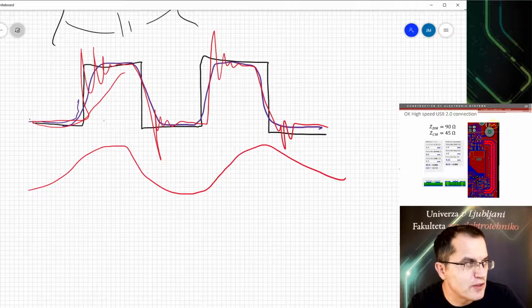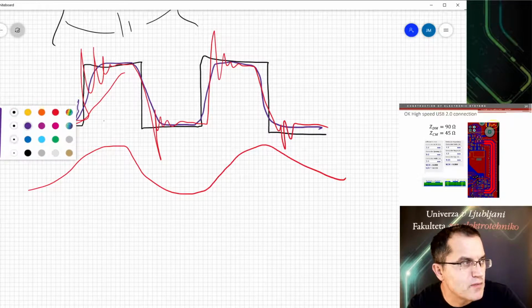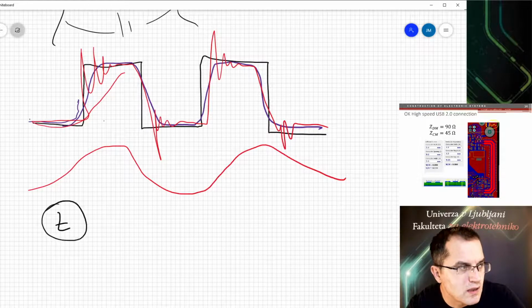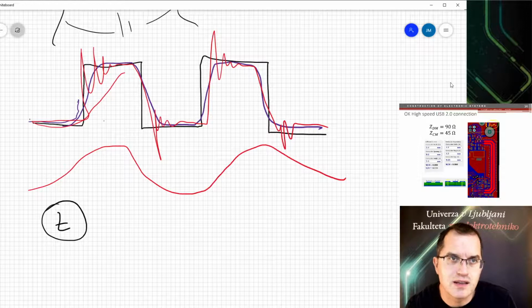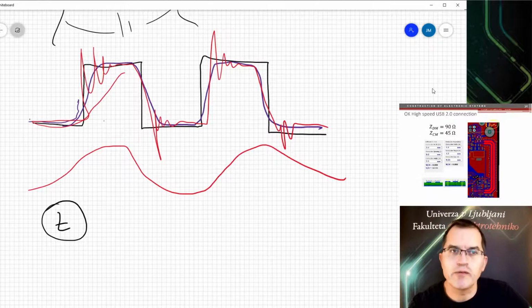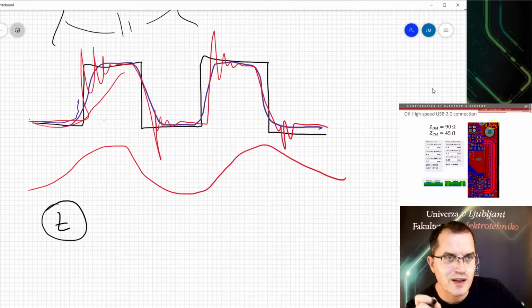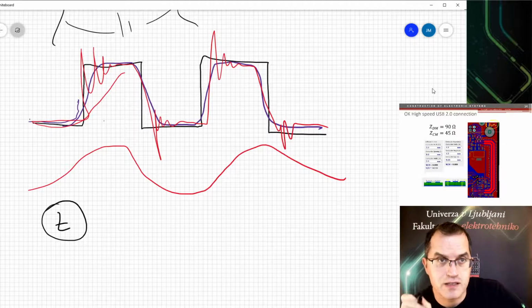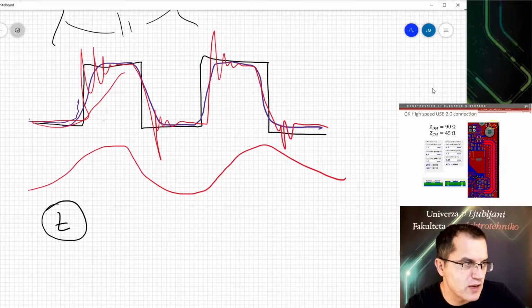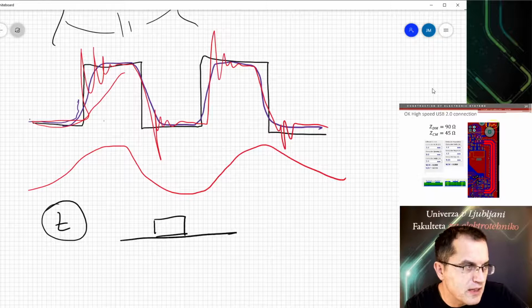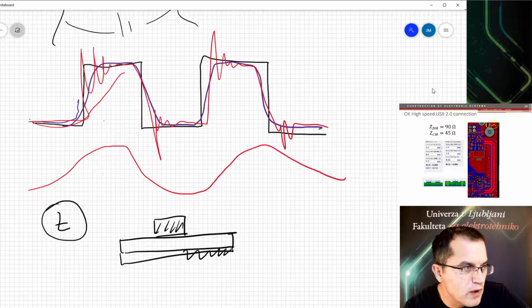And the impedance of the tracks is one of the main properties which, if you keep it at a level defined by the source and the load, would keep your signal as close as possible to the original shape. And we will have a whole lecture about that, so don't worry, we'll come back to that. For now you have to know that impedances of the tracks at high frequency interconnections are very important. And you can keep the impedances of a track very defined by defining its geometry.